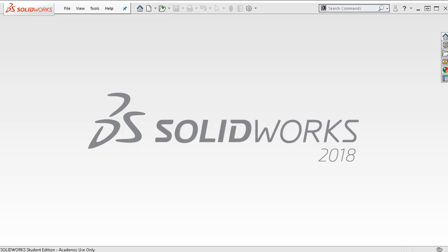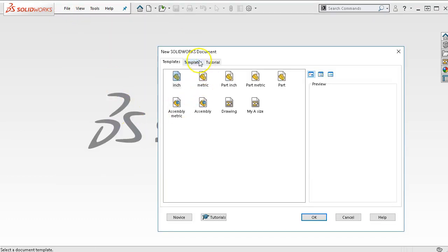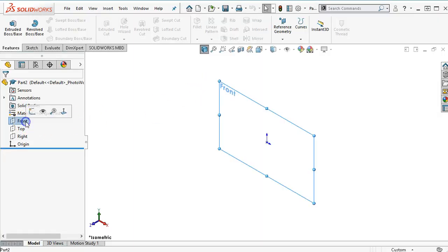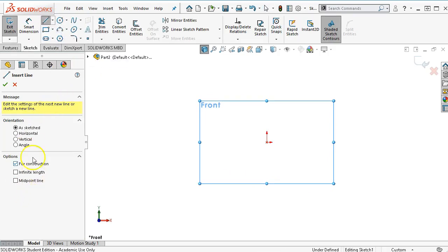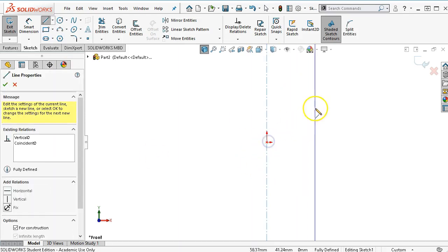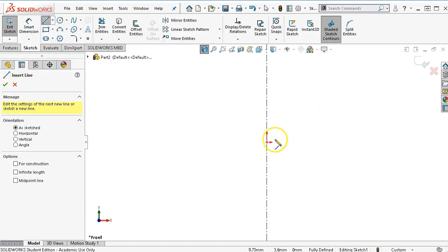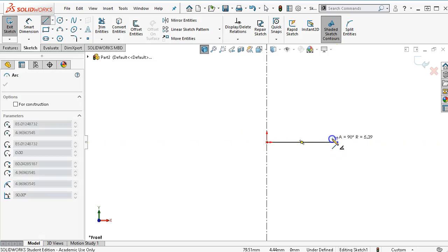Alright, so this is a metric part. Plane and sketch and vertical center line. And if I forget to put the center line in, I can always drop it in later as soon as I realize that I'm going to need it. So I think it's easier just to select or escape and go back into the line command than it is to kind of navigate back out.